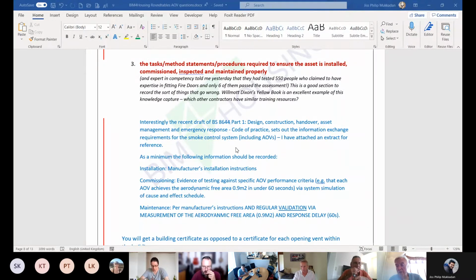There's several different organisations that do very high quality training on cavity barriers, but the individual manufacturers have also got product specific training that needs to be carried out, and therefore what I think we need to be doing is making sure that we're not entirely reliant just on whether somebody's got a certificate or not. We need to also be able to see that they need a checklist.